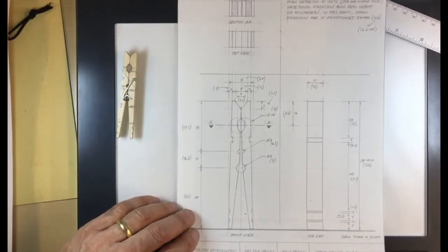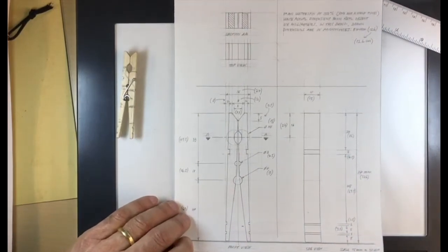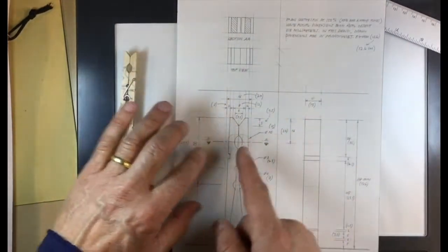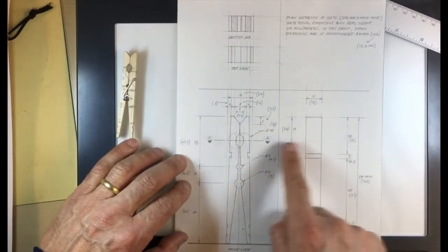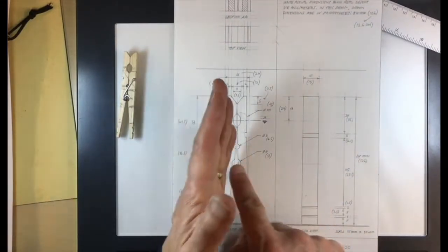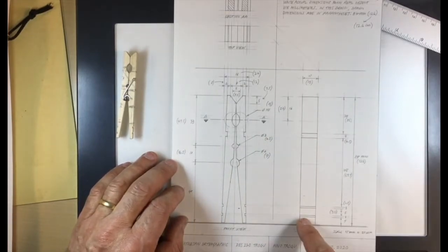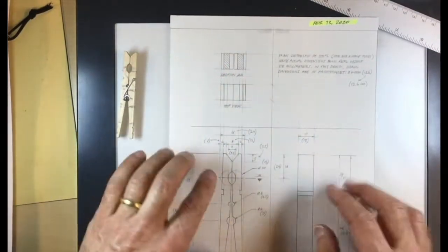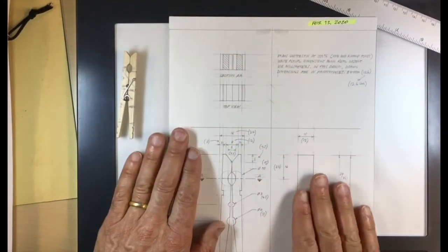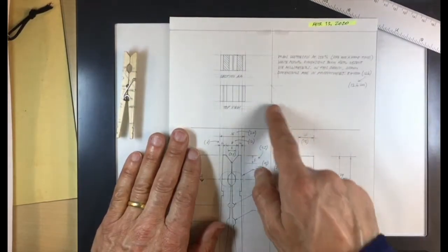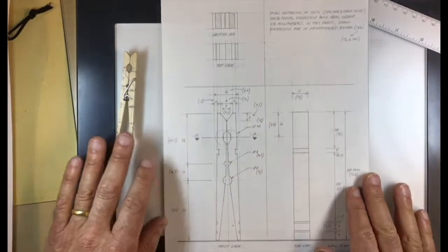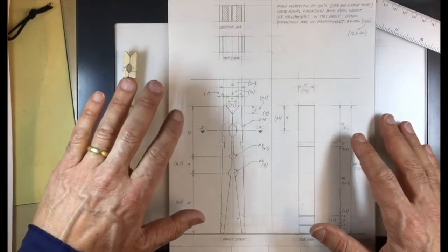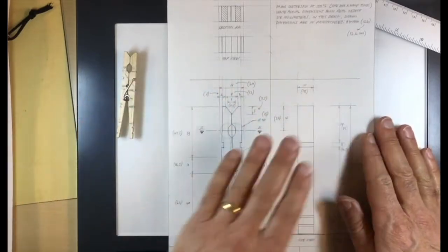And in this drawing, which is again an orthographic drawing of an object, what you do is you draw the main view and then the other views are derived. So you would just project lines from, in this case, the front view to get the side view, and then you just give it its dimension. And the third view would be constructed from a combination of projecting these lines up and projecting these lines sideways using a compass here of the 45. So in short, what you want to do is do, again, as little measurement as possible and just move your lines across to get these other views.